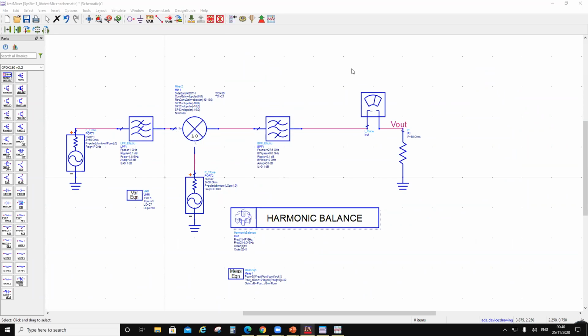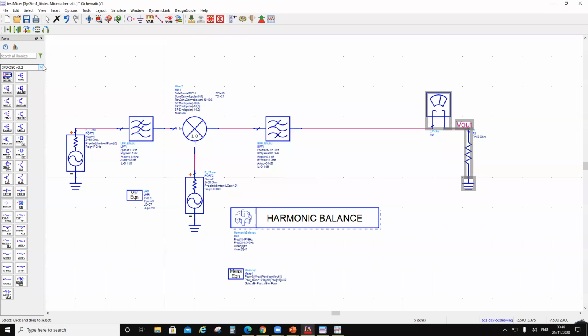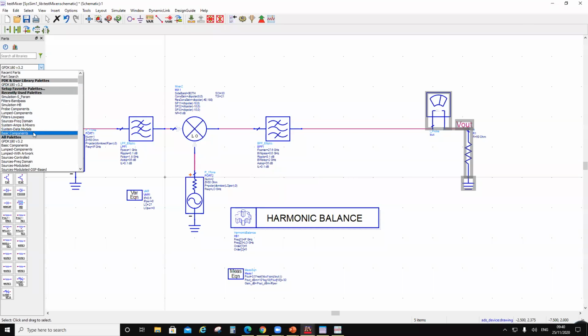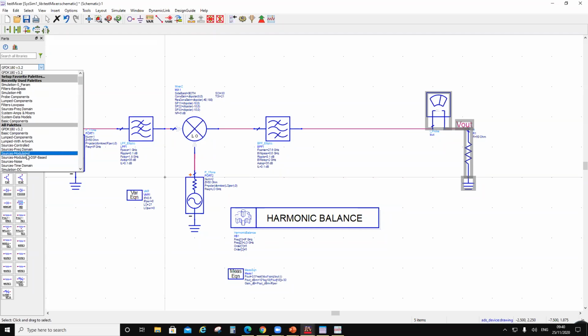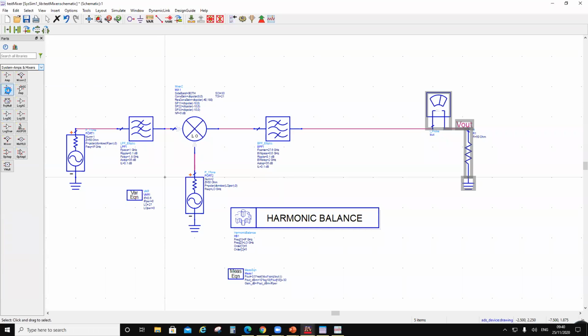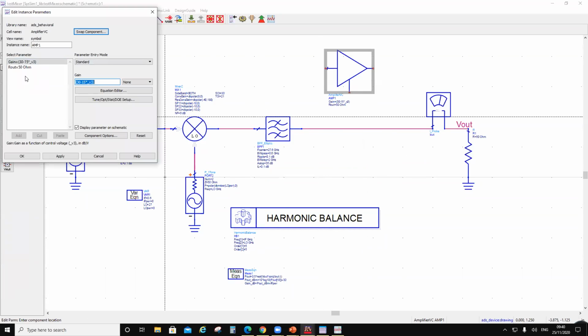Now I will put in gain stages. There are models again here. There is a very linear model, this is called a variable gain. If you go to system, algorithmic system, switch, and not here, maybe amps and mixer, here you have this block. Now this block doesn't have any compression characteristics. It has just an equation.